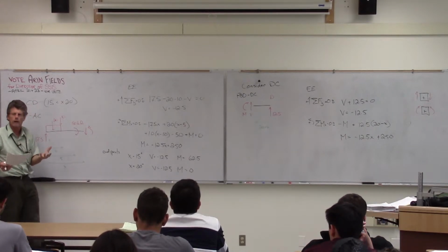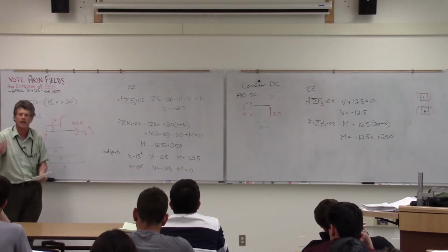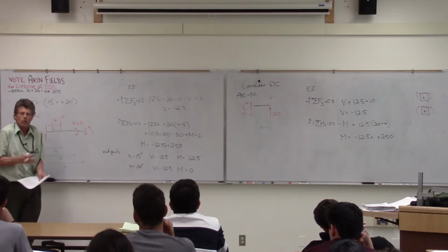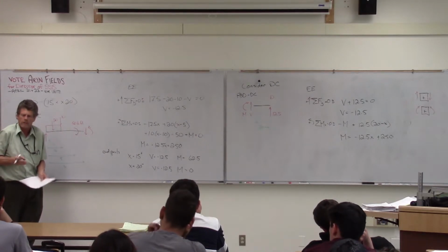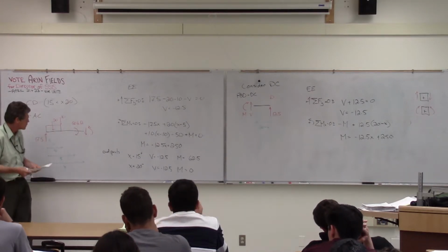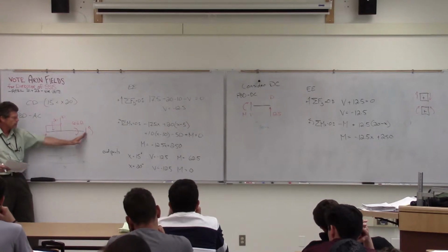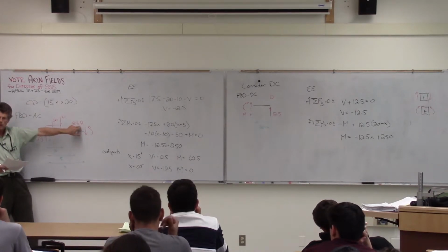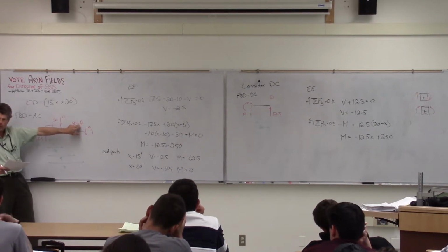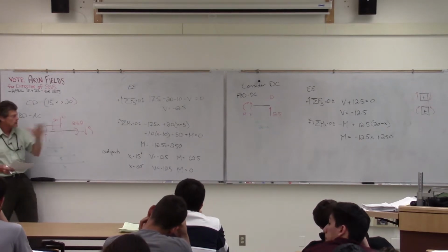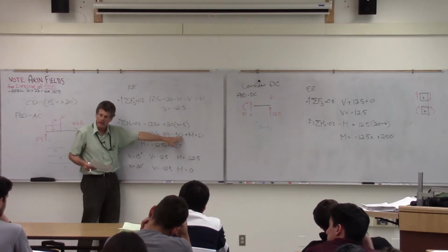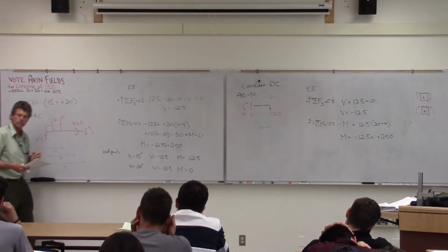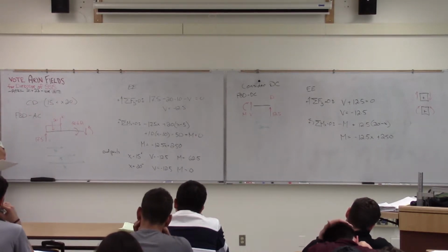Think of a car tire when you're taking the lug nuts off. If you use this lug nut or that lug nut, basically it's going to create the same twist on your tire. It doesn't matter because it sees it as a concentrated twist. So it's not a function of distance. And that's why I put the distance there, but it's already in terms of a moment because it's in terms of force times distance. So we just freely plug it into that equation as a concentrated twist, and then it adds to our equilibrium equation there. Does that make sense?